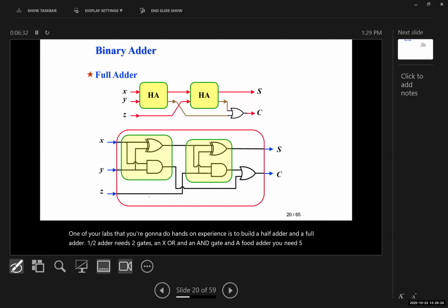So simply by adding an XOR gate instead of the NOT gates, we can create an adder subtractor. If M is 0, then F would be X plus Y. If M is 1, then F would be equal to X minus Y.